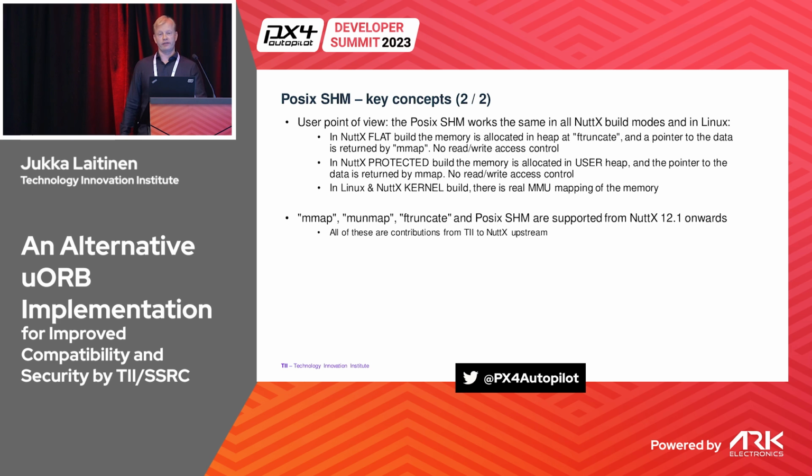And those new interfaces that we are using in our uORB implementation are supported in NuttX upstream from version 12.1 onwards. We have actually made those interfaces into NuttX, so we also have backports on older versions of NuttX, because we started it on older versions, but this is the upstream version where they actually are available.